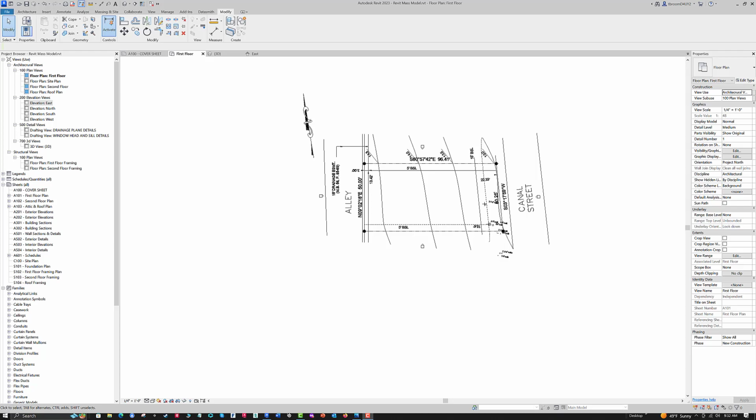When I design, sometimes I design from the outside in, or sometimes from the inside out. It all depends really on the project and how complex it is, and whether the function overrides the look of the building. If I'm doing it from the inside out, then I would create a schematic floor plan before I even started working with the building, to get everything arranged properly so that they function properly. And then I would base my building envelope around my floor plan.